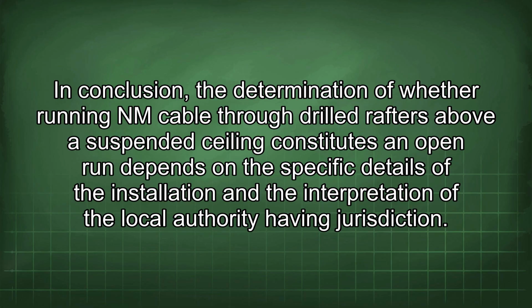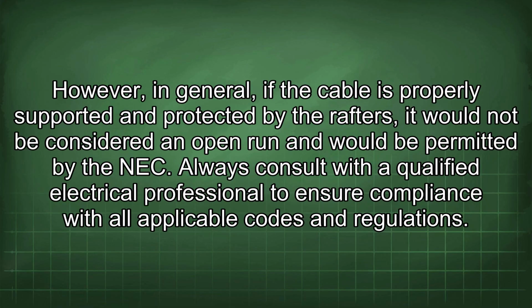In conclusion, the determination of whether running NM cable through drilled rafters above a suspended ceiling constitutes an open run depends on the specific details of the installation and the interpretation of the local authority having jurisdiction. However, in general, if the cable is properly supported and protected by the rafters, it would not be considered an open run and would be permitted by the NEC. Always consult with a qualified electrical professional to ensure compliance with all applicable codes and regulations.